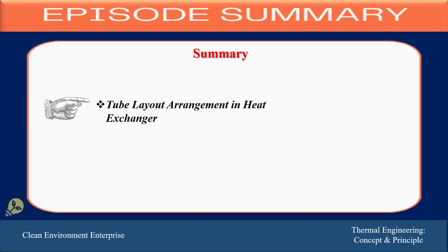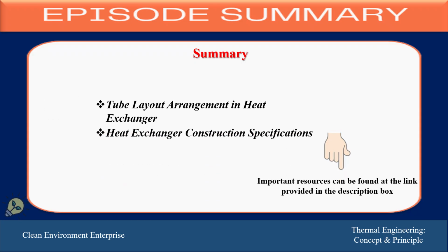They are the triangular and square tube arrangement with a pitch range between 1.25 or 1.33 times d naught, the outside diameter of the tube, and then the heat exchanger construction specifications to be considered before the initiation of the design of the heat exchanger, because these factors affect the final shape of the heat exchanger.